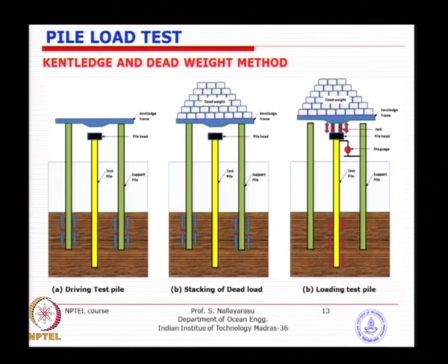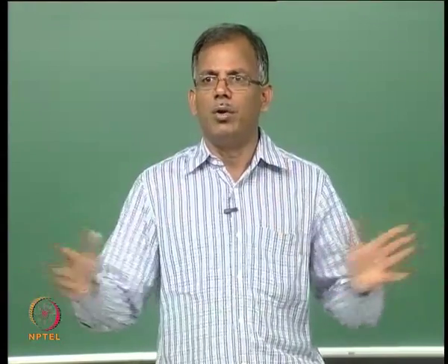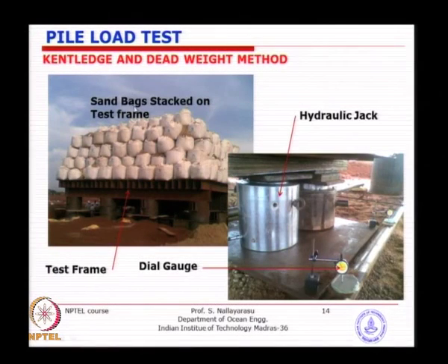So, a typical Kentledge test which is just on land. You can see here, even in this particular case, it was done in one location in Kakinada, where last year, the year before, you can see piles were driven. The ground condition was so bad that you can't spread the load coming from so many sandbags.